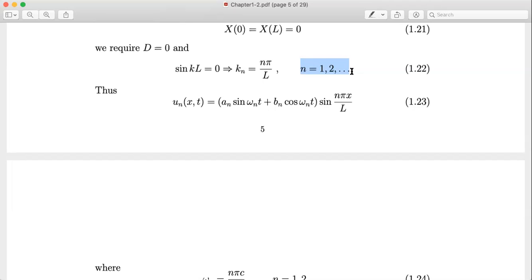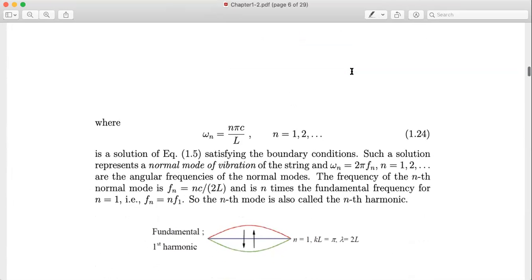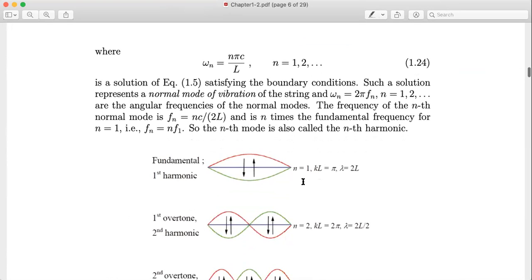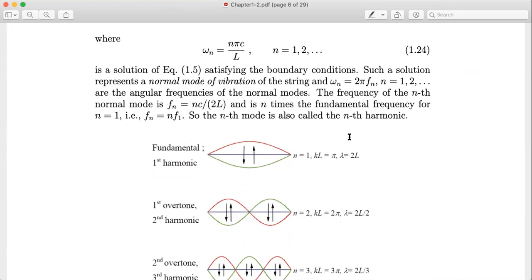That is exactly because we are dealing with a continuous system. If you recall in your 3011 about normal modes of oscillation of a system of masses, the degrees of freedom relate to the number of masses, right? In three dimensions, you can do that calculation. But now we have infinitely many normal modes because we have infinitely many degrees of freedom, because of the continuum. But each of these modes is just of this particular shape. So the dependence on X is fixed, and then it just vibrates with time in a single harmonic fashion.